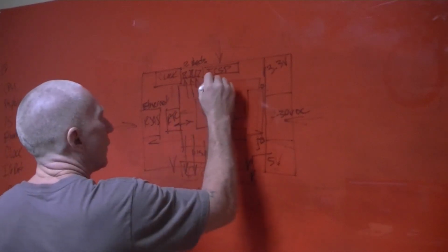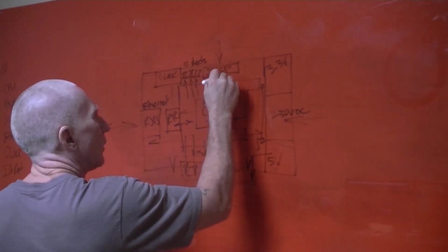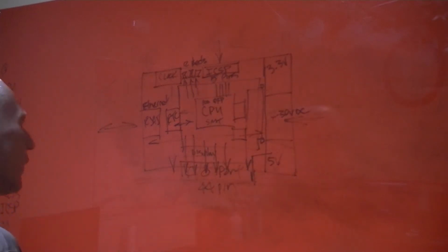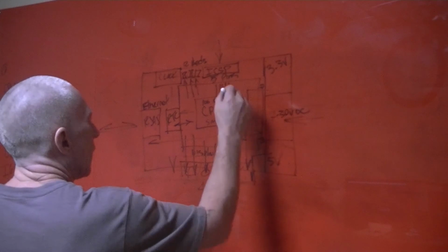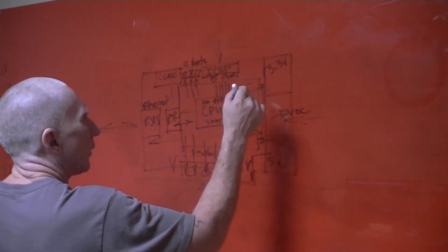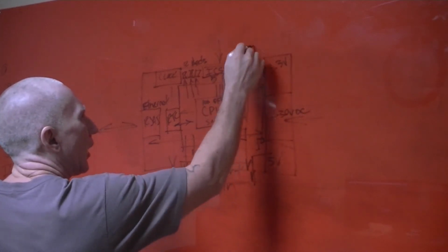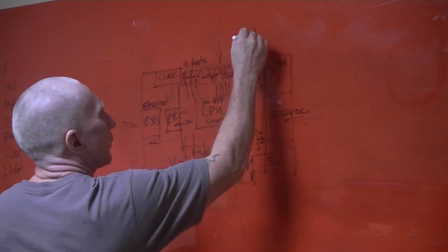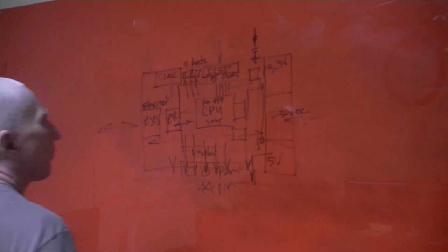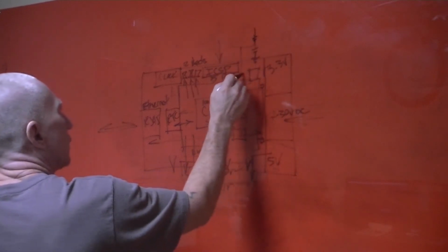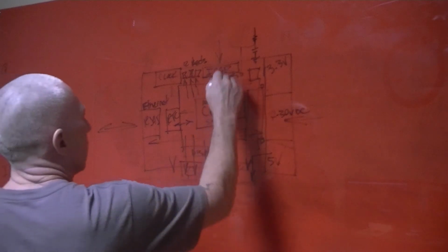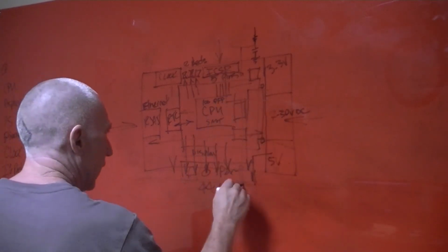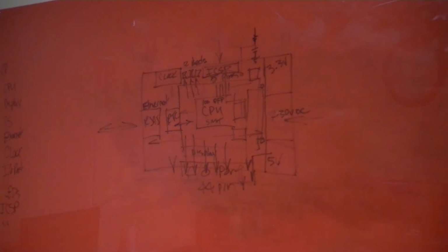There's 5 actual pins used for the ICSP connector. One is the reset. Reset is shared. It's generated here, just a cap and a resistor. And then the reset comes off. It goes to the ICSP connector, then the CPU to the display, and then it's also routed out to the port for a master reset.